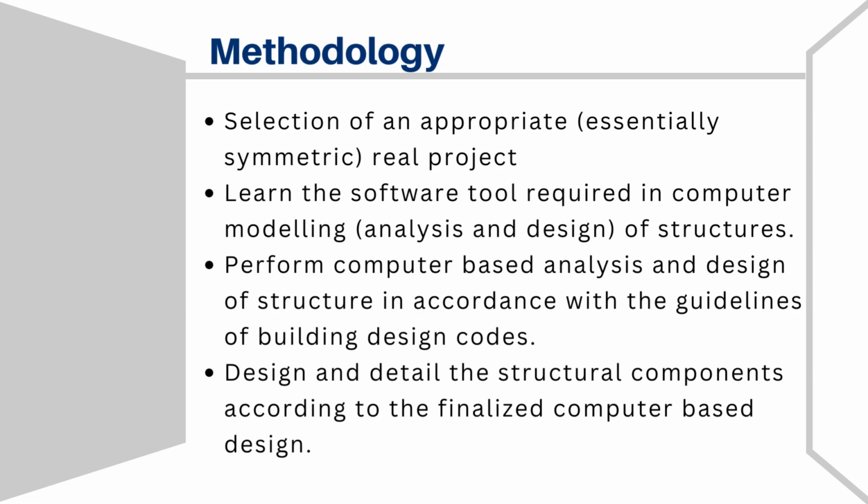ELF, equivalent lateral force method, assumes static cantilever beams, suitable for symmetric, torsion-free, and regular structures. Provides accurate results for short and highly symmetric buildings. RSA, response spectrum analysis, considers mode shapes and modal mass participation. Captures natural response to seismic shaking, requires mode shapes and natural periods for analysis.